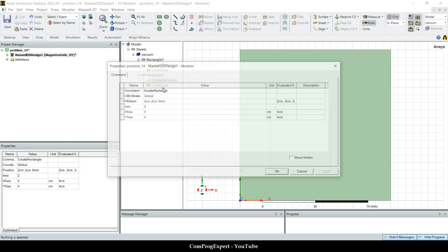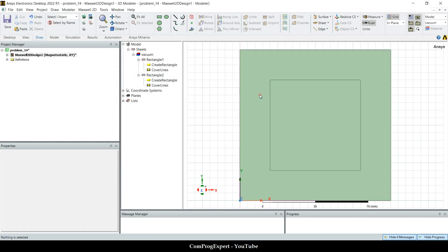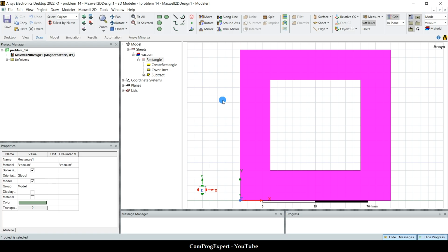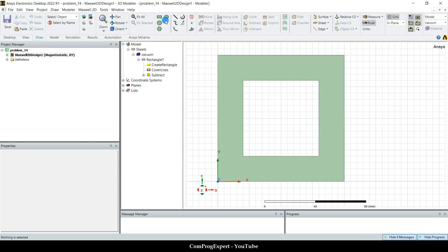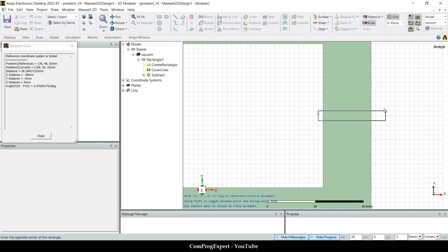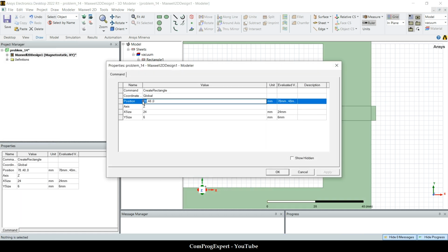No, no, excuse me. This is 6 and 6. So select these two, subtract, save, and we should generate the air gap. As you know, like before, we can set the corner point. This is 5 minus the gap divided by 2. And this is 5.